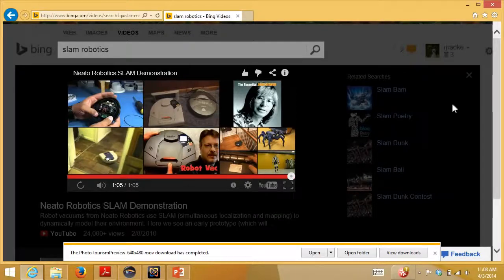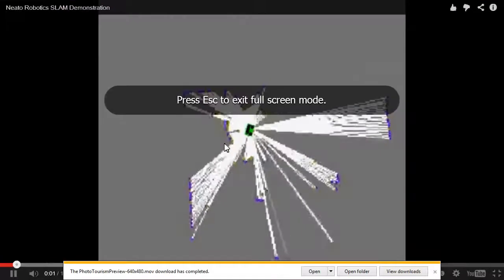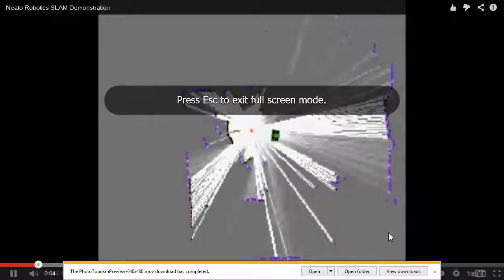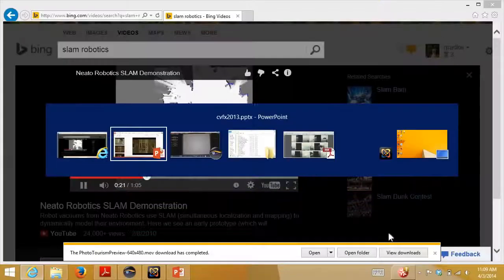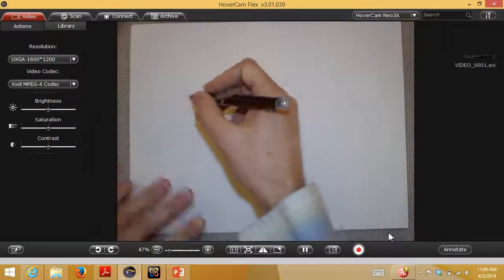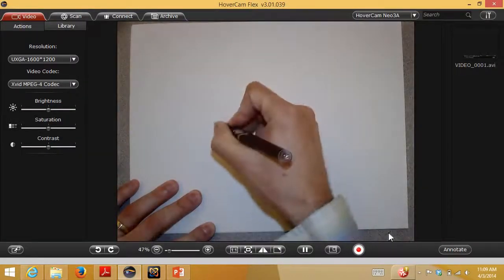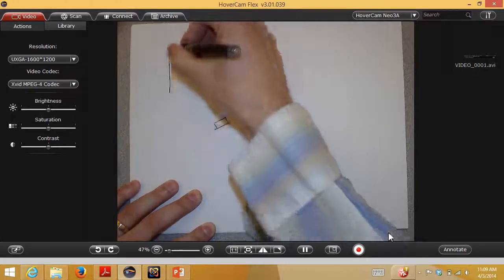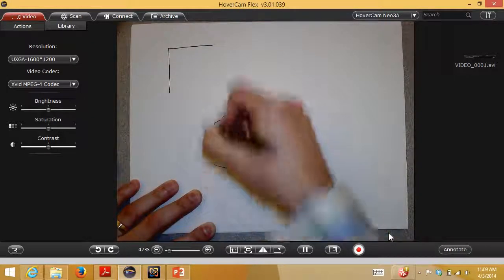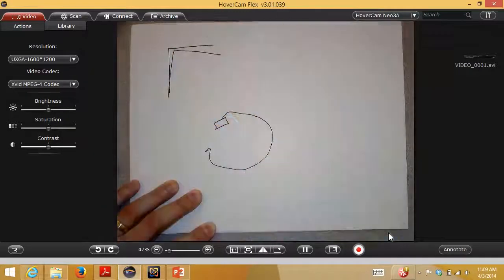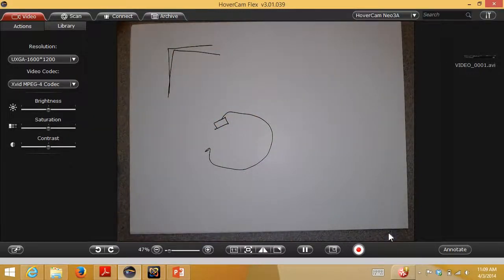One thing that's really important for SLAM is that as the robot sees the same 3D points again as it moves around the world, it's very important to, as they would say, close the loop. Let's see if I can draw this. You don't want a situation where the robot is pointing this way and estimates a 3D wall, then moves around here, comes back, and estimates another 3D wall that looks like this. You want to make sure that everything the robot saw lines up.